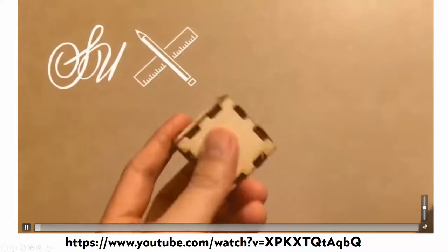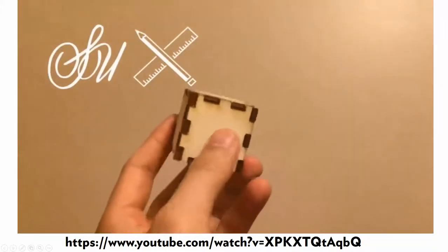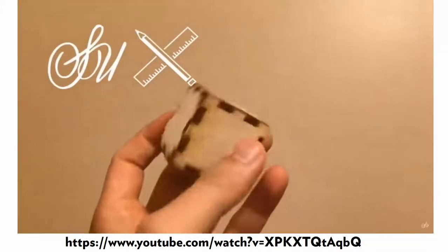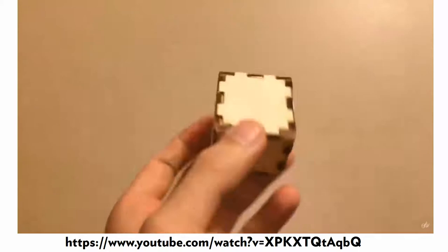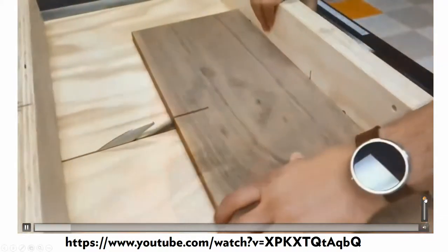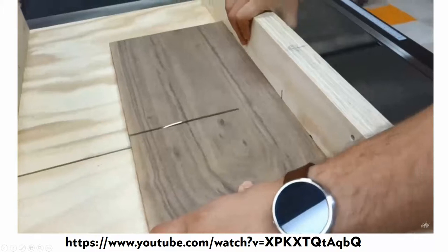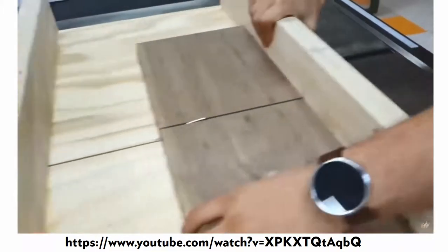One of the first things I made when I got access to a laser cutter was a jointed box. It's a simple project and you're going to learn a lot about laser cutters. And we're going to talk about how to make it right the first time, which requires you to know about kerf. All cutting instruments have some amount of kerf, and that's the area cut away by a tool.